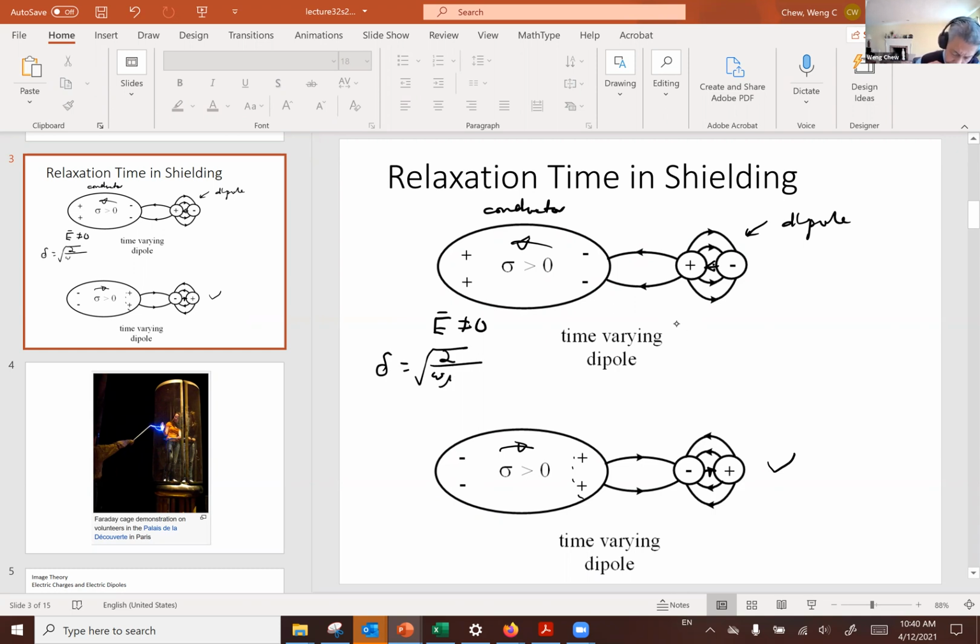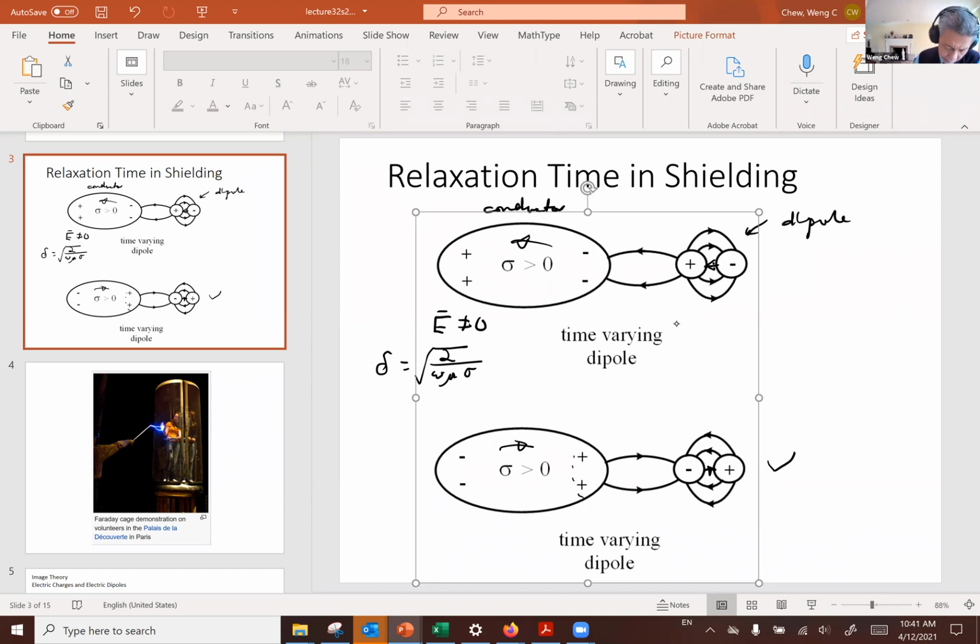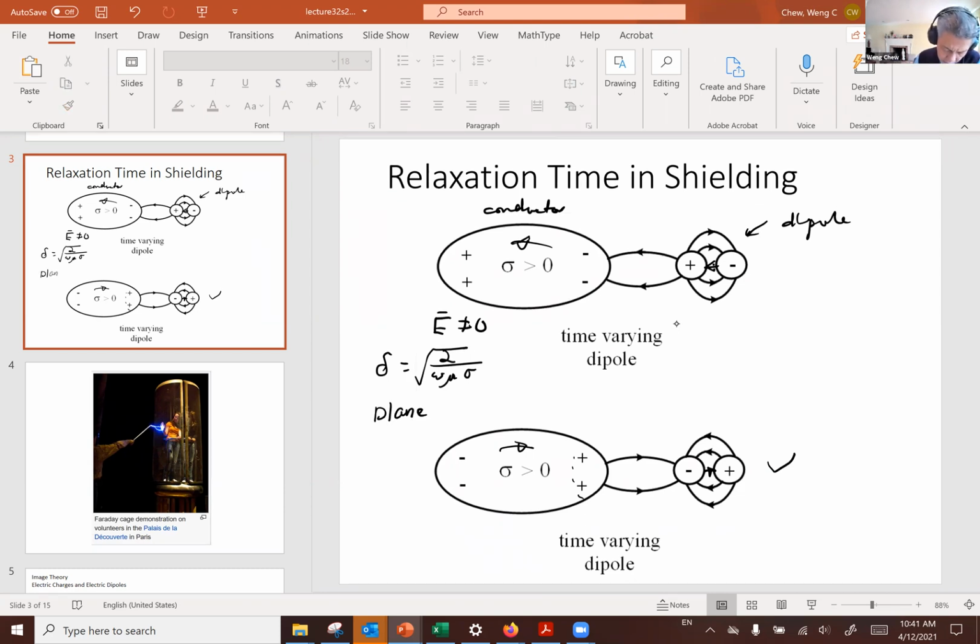And we have earlier looked at the skin depth formula, that the penetration depth of an electromagnetic field into a conductor surface is proportional to this depth. There we did a very simple closed form example using plane wave. But this intuition still holds true, that the non-zero electromagnetic field will confine themselves to a very thin layer close to the surface of the object.